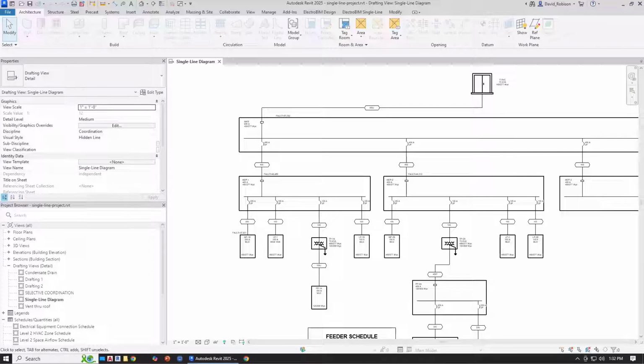The idea is that you as the engineer obviously need to understand how grounds work. We're going to automate some of the sizing for you. Specifically, there are 3 tables used for sizing grounds: NEC 250-66, 250-102, and 250-122. The first one is 250-66. That's for the grounding electrode conductor.